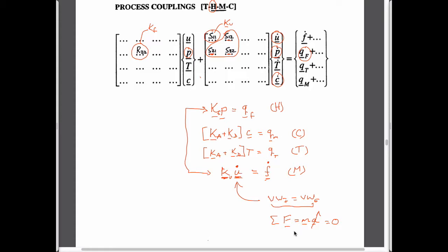And so our finite element statement really is basically looking at equilibrium in x, y, and z if we have a three-dimensional system. And so the equations that we get are in functions of forces. And so the linkage that we have in this is going to be the effects of fluid pressures on those forces. And so what it will turn out to be is that the linkage is as a body force, and it's equivalent to a change in pressure with length.